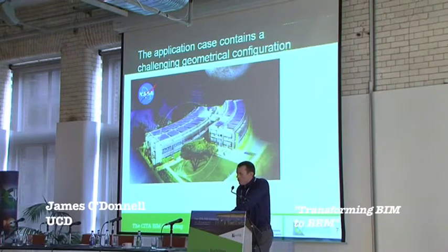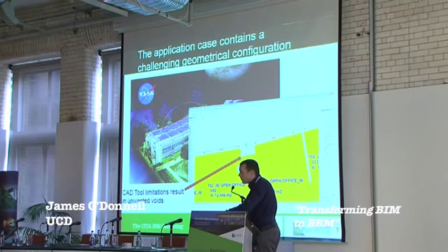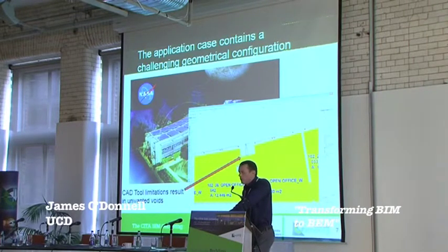So we have a number of issues that arise due to the modelling capabilities of this particular tool and of the CAD tools in general. We see here the concentric circle segments have been simplified to linear sections on the facade for prefabricated construction purposes, and it ends up resulting in little slivers that are not defined within the model. These are tiny sections, but due to the nature of the heat transfer required by the energy simulation tools, it generates a number of errors for our post-processing. So just be aware of errors like this, and again the high tolerance requirement of a Space Boundary Tool.